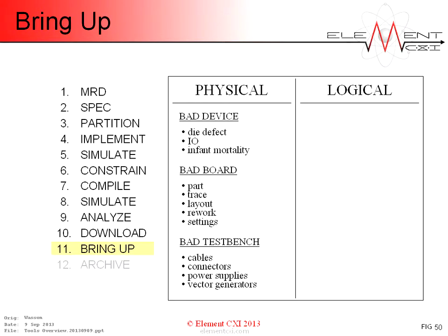In addition to bad data arising from physical problems, logical problems usually arise from misguided assumptions. Simple things like getting signal levels wrong, high instead of low, or missing a pull-up or a pull-down on a tri-state line. Unexpected initial conditions like reset states or register or memory contents. Errant accesses using the wrong storage address which work during simulation but not in situ.